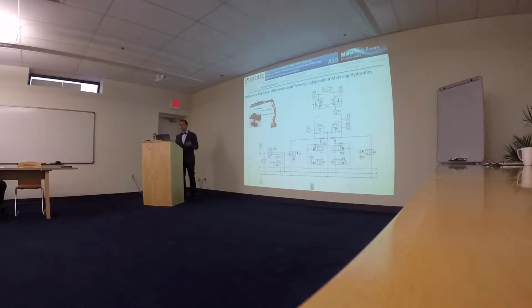So this poses a challenge in the controller, because now, in order to, for example, extract the cylinder, we have to command SP2 and SP4. So SP2 will be the meter in edge, and SP4 will be the meter out. So we need always 2 inputs for controlling the machine. And the same story for SP1 for the retraction of the cylinder.